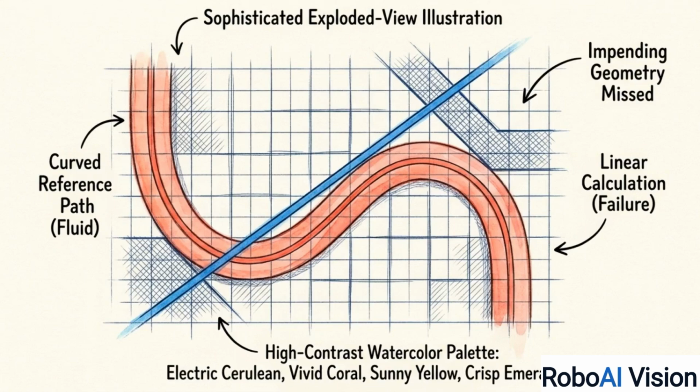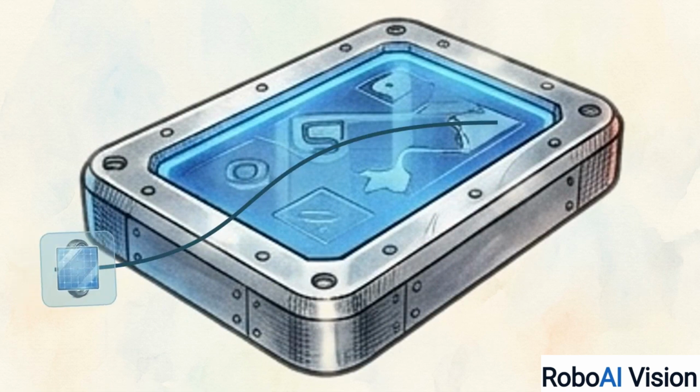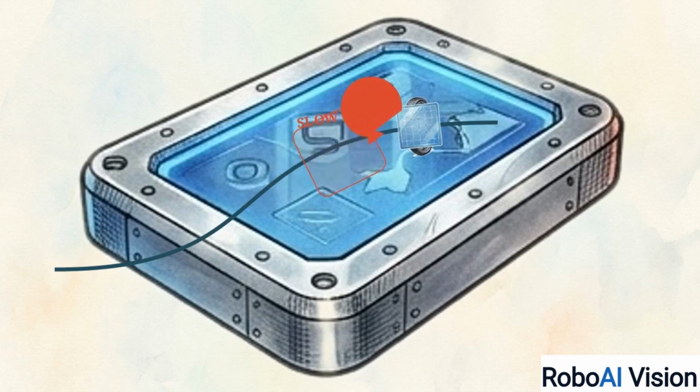But unicycle dynamics, where steering directly impacts forward speed, are highly nonlinear. As the unicycle icon hits a high curvature turn, the actual physical state deviates from the linear assumption. The linearization matrix becomes increasingly inaccurate, and the quadratic programming solver breaks down, resulting in trivial or stalled inputs.